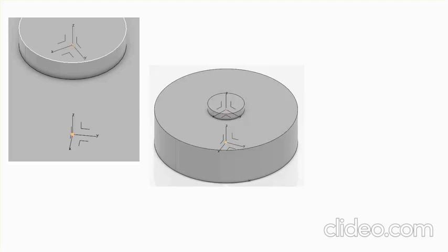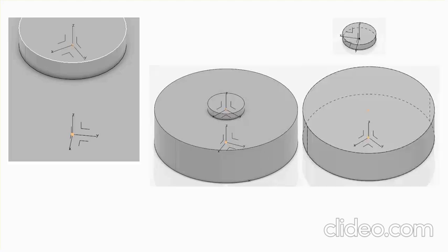Also notice that I have rotated the disc so that it's not aligned with the shaft up there, essentially the dummy shaft. There's a reason for that because we're talking about free vibration. Therefore, you need to have some offset between these planes, these two objects. So I'm using roughly 20 degrees. Small scale oscillation.